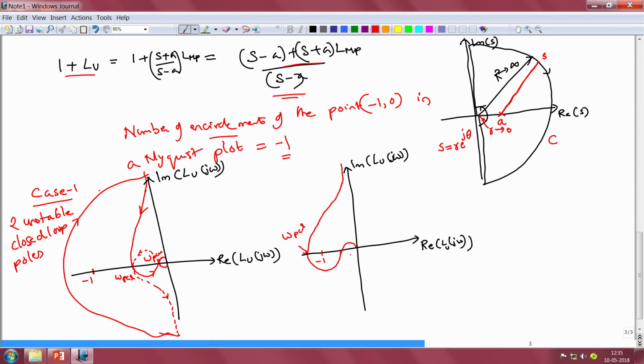The Nyquist plot along the negative imaginary axis will be the mirror image of this Nyquist plot about the real axis and would therefore look something like this. And the small D shaped contour near the origin gets mapped to this huge D shaped contour that starts at the negative imaginary axis at close to -infinity and goes towards the positive imaginary axis close to +infinity. Once again this is supposed to be a semicircle, but owing to shortage of space and my limited abilities as an artist, it looks like a distorted circle.